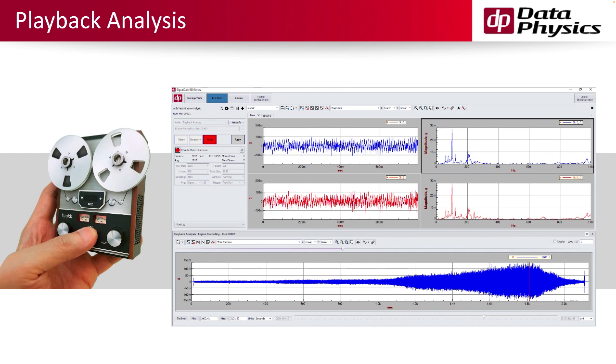So if you're using a rectangle window, applying a Hamming window or a flat top window, how does that affect the data? In a different case, you might need to increase the number of frequency lines to get better resolution in the frequency domain, or apply a different averaging technique. The idea is to understand the data from different viewpoints and perspectives to capture the complete picture.